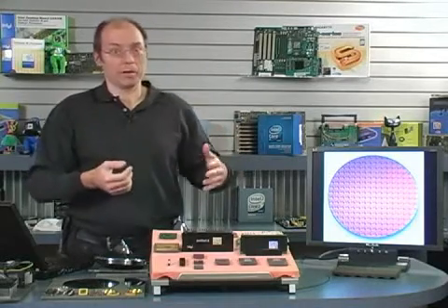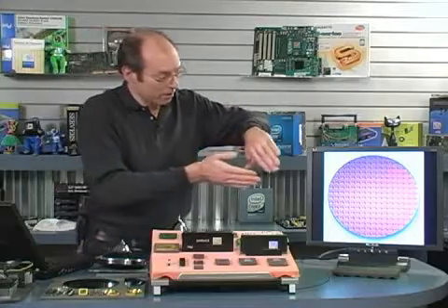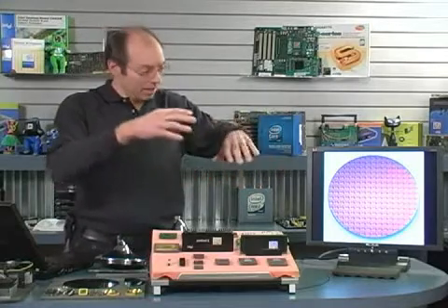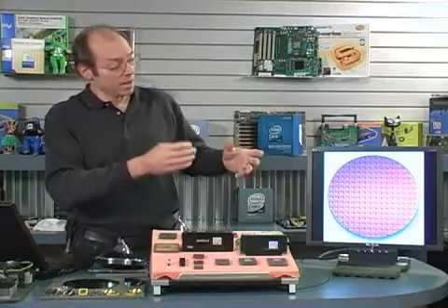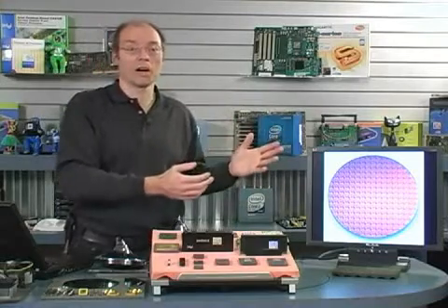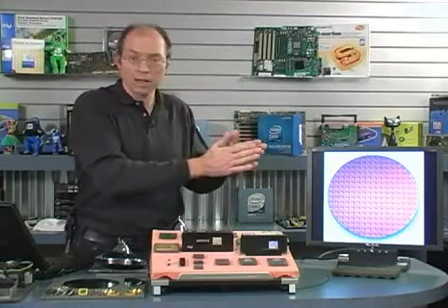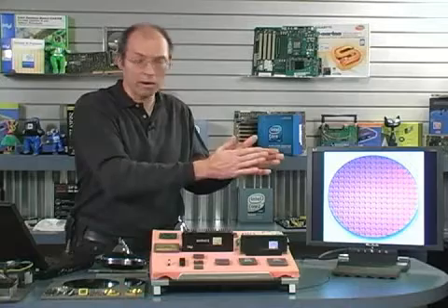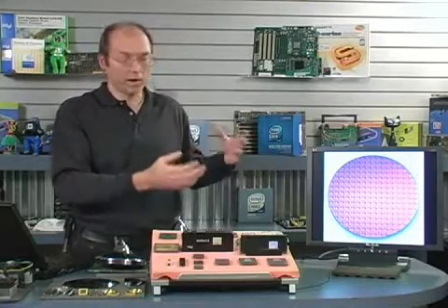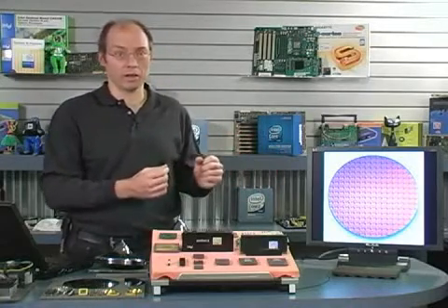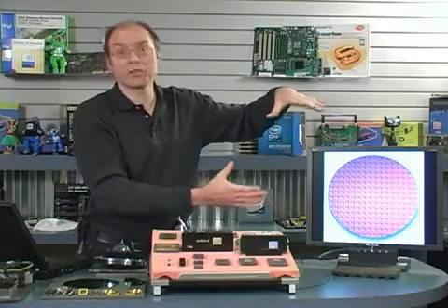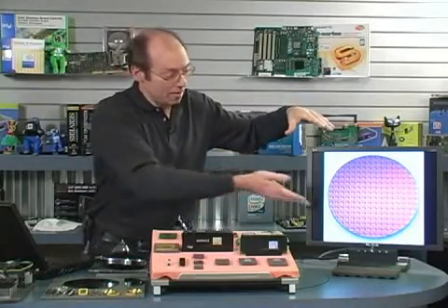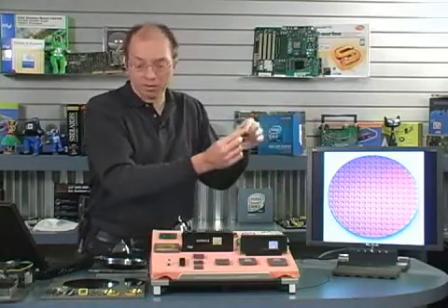And through the photolithographic process, material is coated onto the wafer, then it is etched with the ultraviolet laser, then portions are washed off, and we literally have like a cake building process, layer upon layer upon layer, until this very complicated series of circuits is assembled. Then, once the wafer is complete, the individual die are cut out of it. So we end up with individual square processor die.